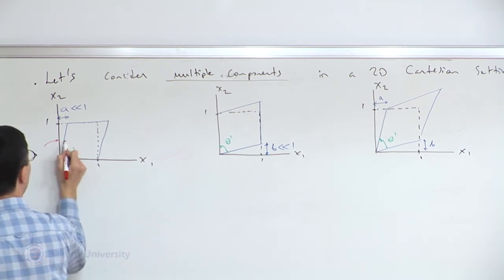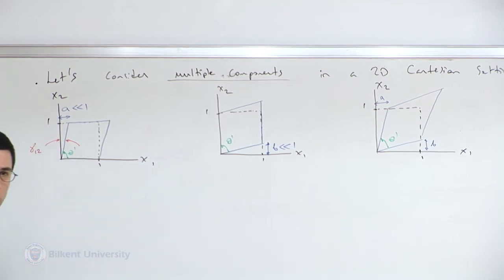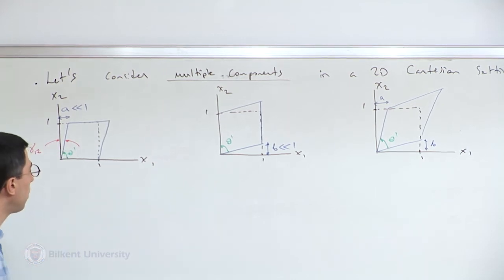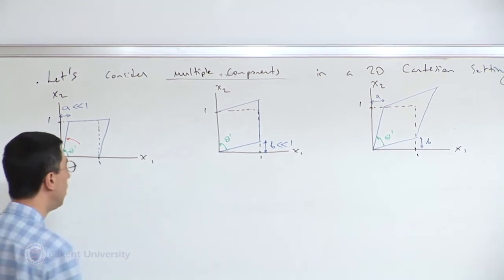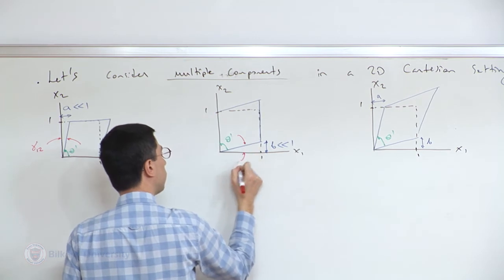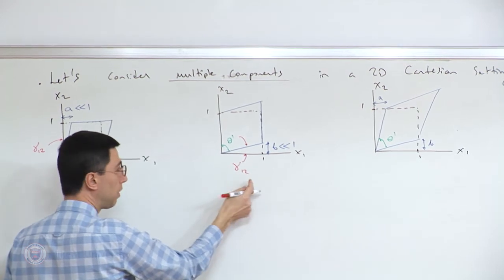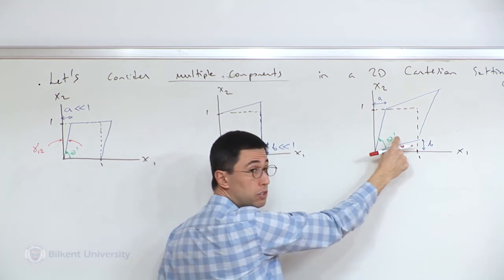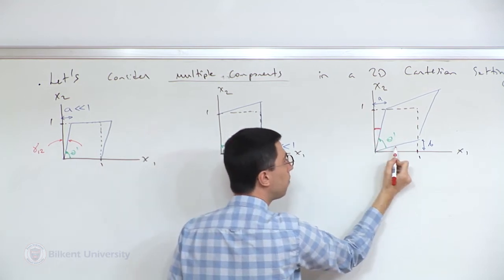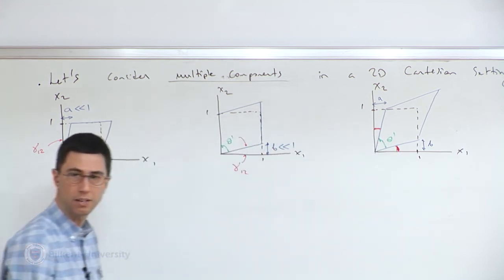So this angle here is equal to gamma 1, 2. Right? I'm not putting average, assuming these deformations are very, very small. This is going to be exactly the pointwise shear strain, gamma 1, 2. I could have written gamma 2, 1. It doesn't matter whether I write 1, 2 or 2, 1. And here, the old angle minus the new angle is a sum of these two angles. So gamma 1, 2 is the sum of this angle with that angle, right?